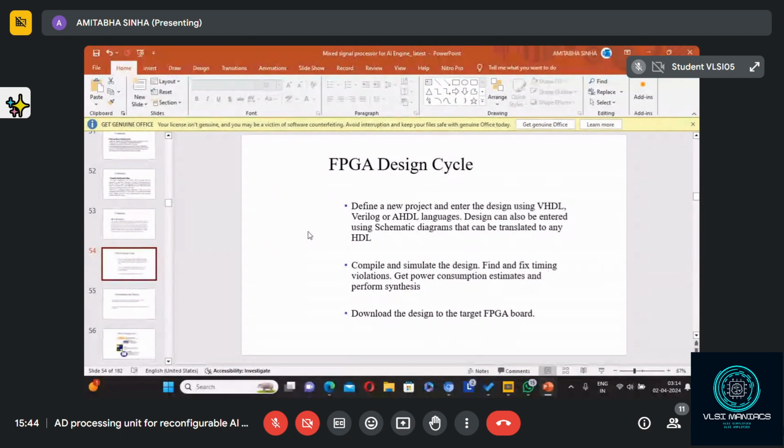Now, state diagram consists of what? Some circles and some arcs. Whenever there is a transition from one state to another state, we define it by an arc. And we also define the name of the states. Like if there are 4 states, you can write 00, 01, 11, 10 in that way. Whenever there is a transition, it goes from one state to another state. So state transition, and also what will be the output, we indicate, we write. So in that way, you can draw the diagram.